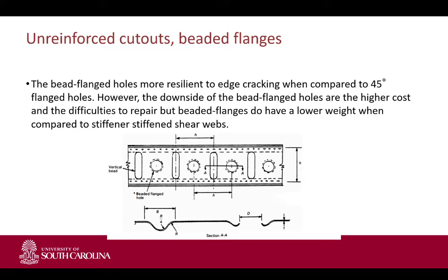But often we see that those aircraft are way over designed, so they will fail at, say, 20% above ultimate, or 10% above ultimate. But again, at that stage everything has been recorded. That can be helpful to evaluate your numerical analysis and your design steps down the pipeline.